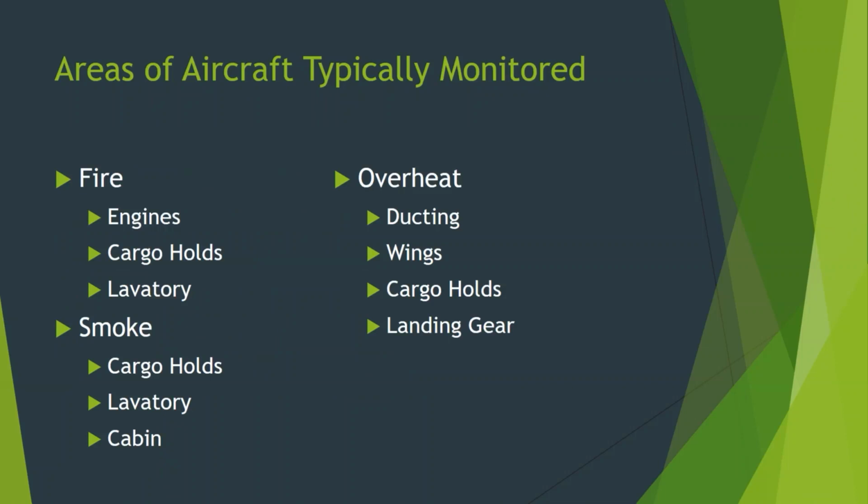The APU is usually not even in the belly area anymore. No, not the air cycle machine. Think more structural. What runs right through that landing gear bay? Your main spars. If those get too hot and start to get weak, your wings no longer stay on your airplane. So if you get a big fire down in that landing gear bay, you don't want to weaken the structure.